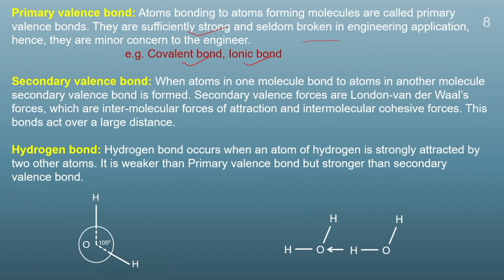Whereas, when atoms in one molecule bond to atoms in another molecule, secondary valence bonds are formed. The secondary valence bonds are London van der Waals forces, also known as van der Waals forces. These are intermolecular forces of attraction, and this bond acts over a large distance. Therefore, in a clay-water system, the secondary valence bond plays a very important role.